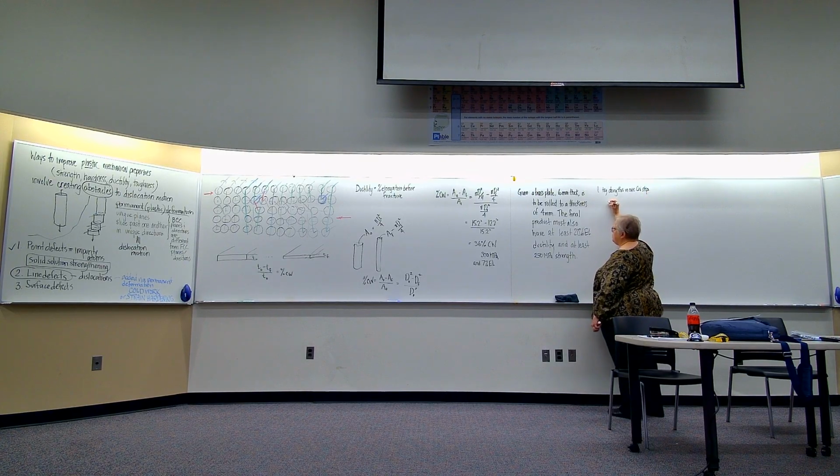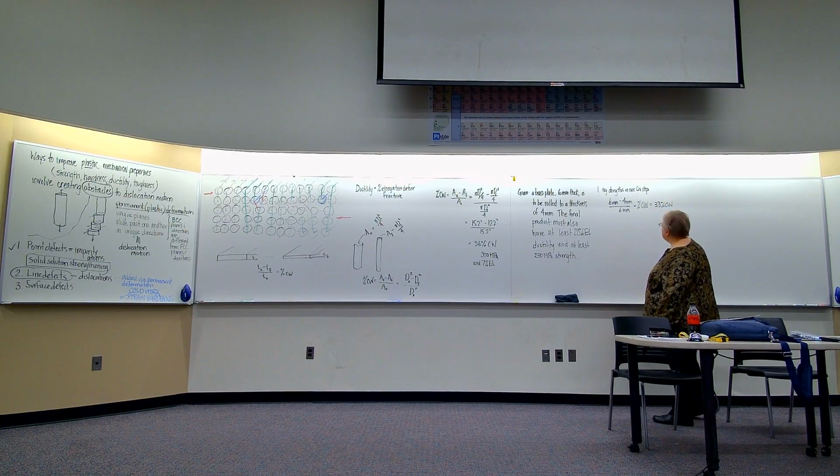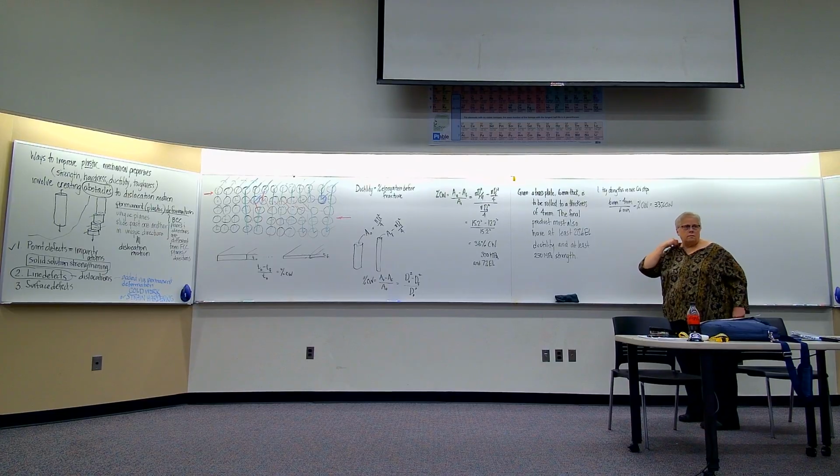I'm going from 6 millimeters to 4 millimeters over the original 6 millimeters. That's my percent cold work. So 2/6, that's 33% cold work. Right?